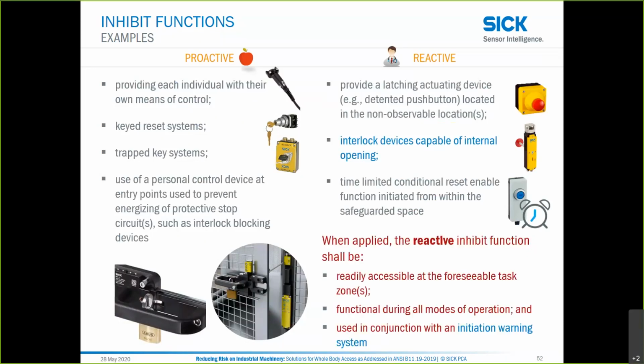And what's important to understand is with the reactive devices, because they don't stop the scenario from occurring, there's an additional requirement that these reactive devices have to be readily accessible wherever people are exposed. They always have to be functional during every mode of operation, and also that they have to be used in conjunction with an initiation warning system, which is another measure we'll get to here in a few moments.